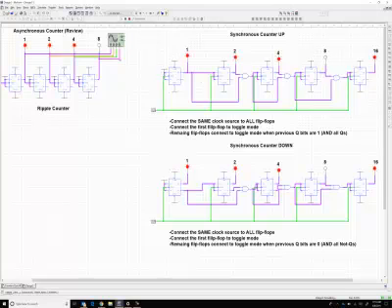So there you go, just to highlight, the previous counters had one input clock going to the first one, and then the clock frequency got divided as it rippled through. And the JKs were always set to power. What we do differently for synchronous counters is that the clock is all coming from the exact same clock source, and what we do is we control when we have a 1-1 ready at JK for it to toggle.